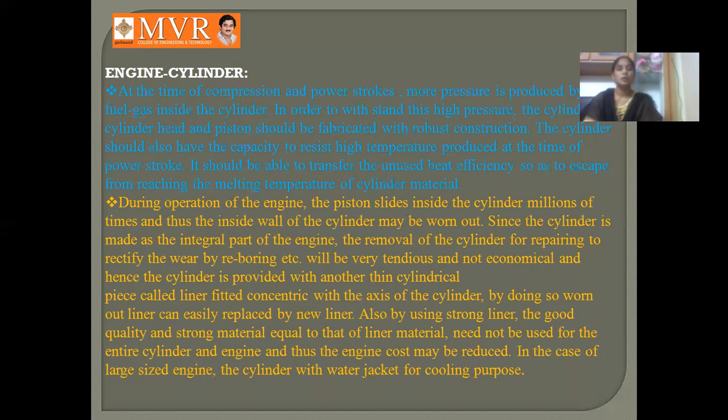During operation of the engine, the piston slides inside the cylinder millions of times, and the inside wall of the cylinder may be worn out. Since the cylinder is made as an integral part of the engine, removal of the cylinder for repairing to rectify the wear and reboring is difficult.